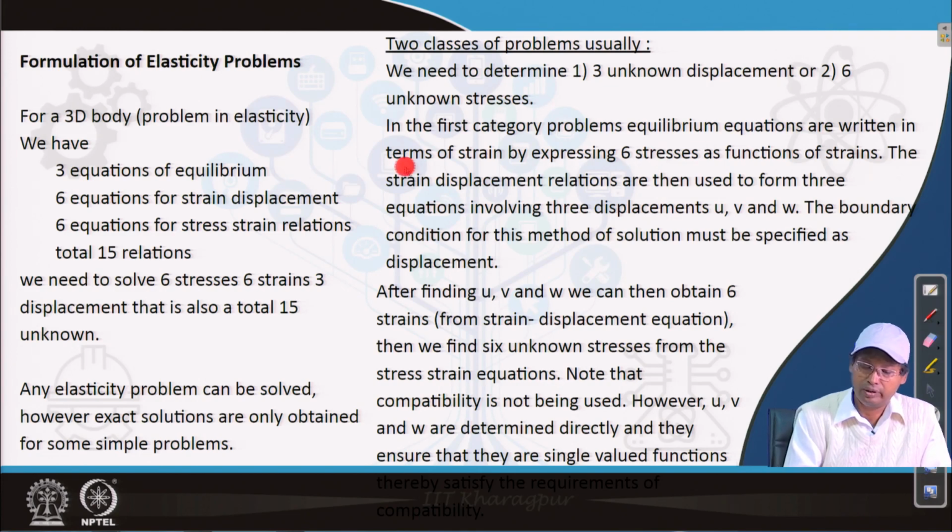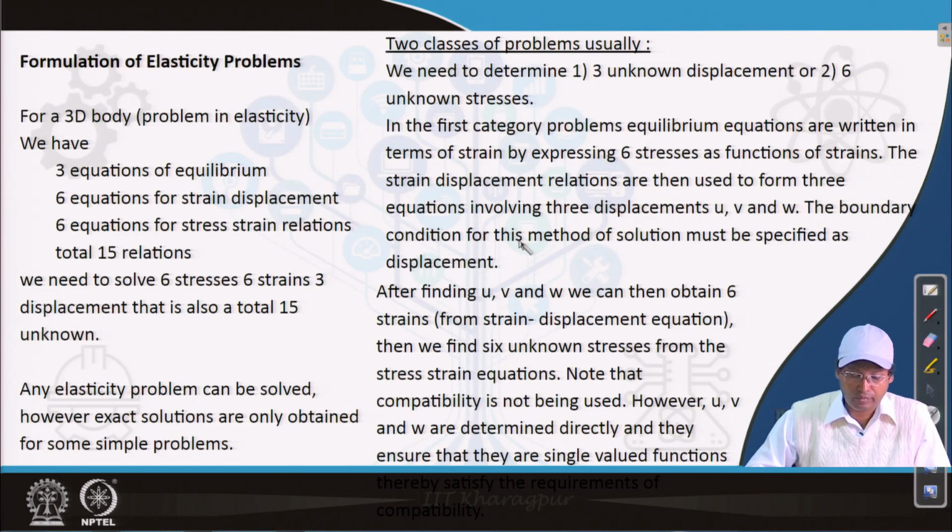The strain displacement relations are then used to form 3 equations involving the 3 displacements u, v and w. The boundary conditions for this method of solution must be specified as displacements.